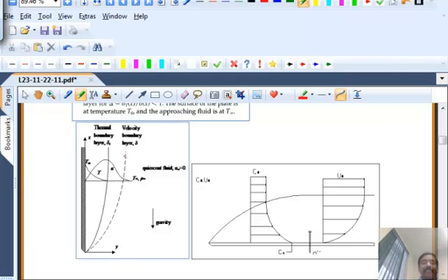These are some of the sketches. For natural convection, again, in this case there is no forced flow. What you have is a plate that is heated and there is fluid surrounding it. So what would happen? The fluid velocity is going to be zero at the wall. It's going to increase and then it's going to be stagnant. So there is no flow outside of the velocity boundary layer. All the flow occurs only near the plate.